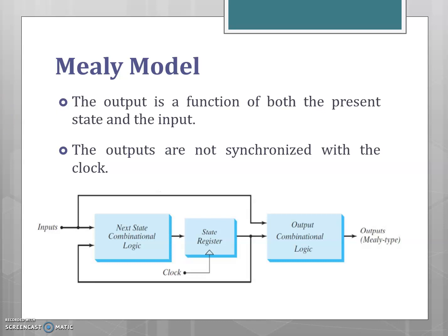The structure of the Mealy model is shown in the figure. Here, the output depends on the present state as well as the input. So, the outputs of the sequential circuit are not synchronized with the clock because the output may change if the input changes.